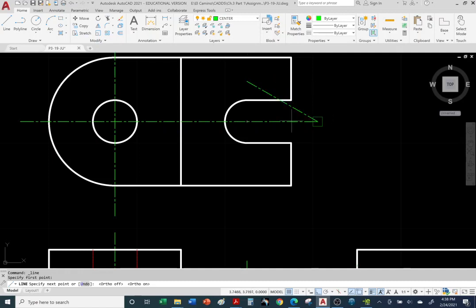But it's still going to try and snap. So it will allow you to snap, so be aware of that. It's two options that are fighting each other. You have ortho and snap fighting each other, and that's why the line is disappearing and reappearing. Okay, and click and hit escape. All right, so that is ortho mode.